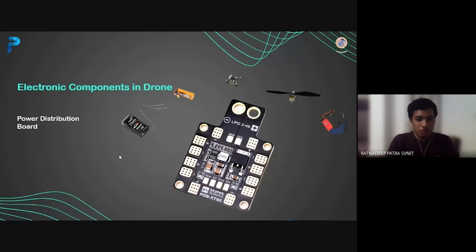Then we have the power distribution board, PDB. One of the major problems that we face while giving power supply to all of these components is that the BLDC motor requires higher voltage, around 9 volts or 11 volts, but our other components like the receiver, flight controller, and ESCs require just 5 volts power supply. Due to this, we require a power distribution board. A power distribution board directly takes voltage from the battery and reduces it to 5 volts, so that this 5 volt supply can be provided to all other components, and simultaneously it connects the battery directly to the BLDC, so that a constant supply of 9 volts or 11 volts can be supplied to the BLDC, which requires higher voltage.